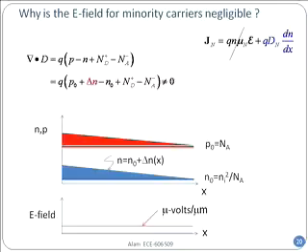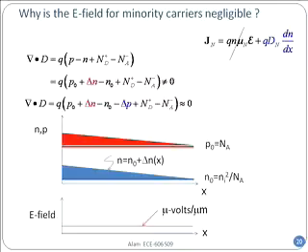Now, do you see here that this region is almost charge neutral at every point, but it's not density neutral at every point? The density is no longer the same, right? At every point, density is non-uniform, but charge-wise, it's essentially more or less the same. And as a result, that delta P flowing in from the contact is almost equal to 0.